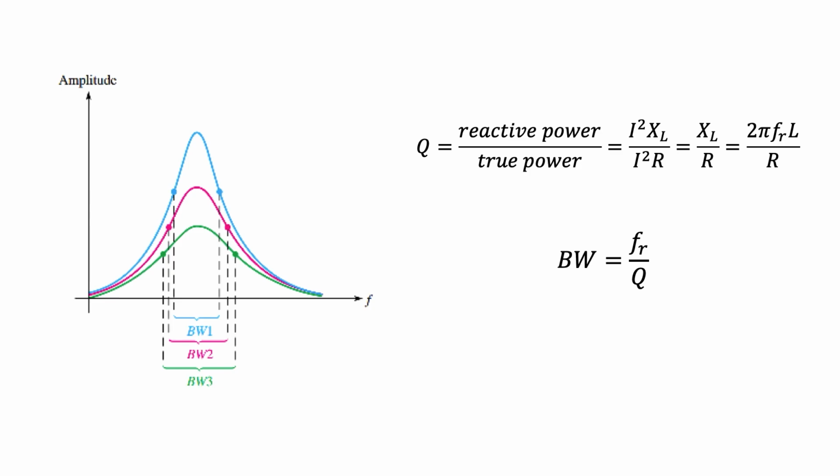We also characterize the resonant circuit in terms of its selectivity. Basically, the narrower the bandwidth, the greater the selectivity. In the figure above, the blue curve has the best selectivity due to the narrower bandwidth. The quality factor is another parameter that characterizes bandpass filters. It is defined as shown. It is related to the bandwidth as shown. Thus, the greater the quality factor, the smaller the bandwidth, the better a circuit is.